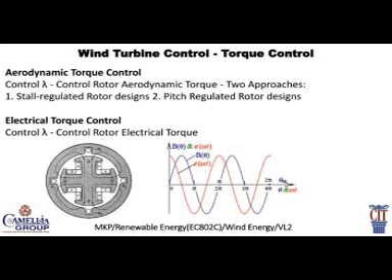The reactive power generated by a synchronous machine can be adjusted by controlling the magnitude of the rotor field current. Unloaded synchronous machines are also often installed in power systems solely for power factor correction or for control of reactive kVA flow.